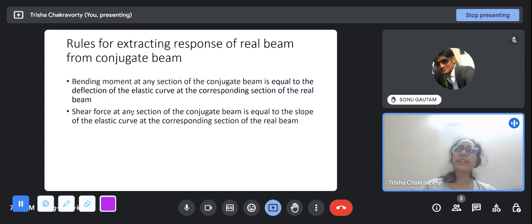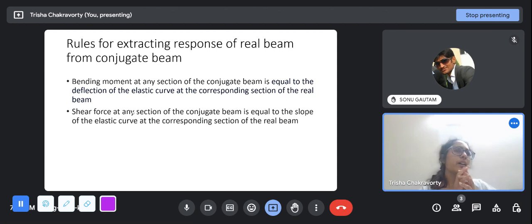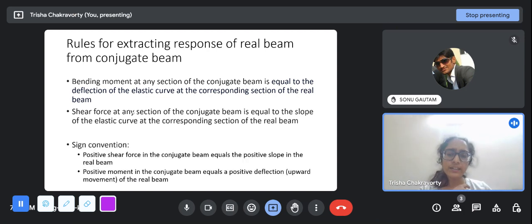because most buildings we see around us are concrete buildings like RCC, reinforced cement concrete, and concrete is very weak in tension. So if we are analyzing a beam, we have to know on which side tension is coming and on which side compression is coming, because on the tensile side we have to give steel reinforcement to take the tension. Concrete is supposed to be strong in compression. So if we are sure that one part of a beam or a column will always be under compression no matter what the loading condition is, then we need not give any steel, and that is how we make a design economical. So sign is very important in structural analysis, in deflection, slope, shear force, bending moment, anywhere.